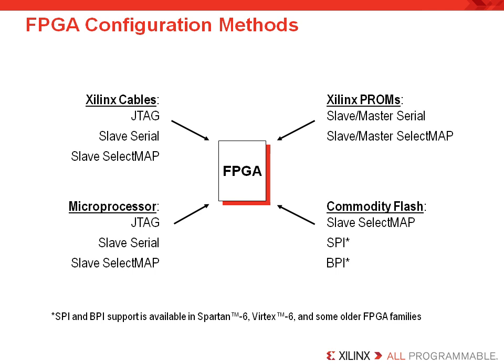Well, there are lots of configuration possibilities to consider. The first we're going to consider is configuring via a Xilinx download cable. These cables allow the user to reconfigure their FPGA with only a download cable and their computer. The configuration modes described are used primarily for prototyping and debugging a design. These cables are low cost and are typically used to configure the FPGA in a JTAG configuration mode. We will discuss the additional hardware available in the basic FPGA Configuration 2 module.